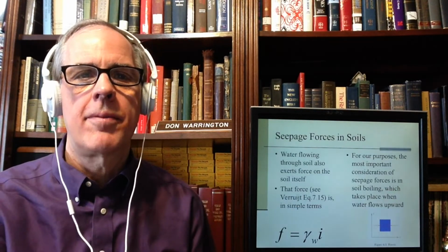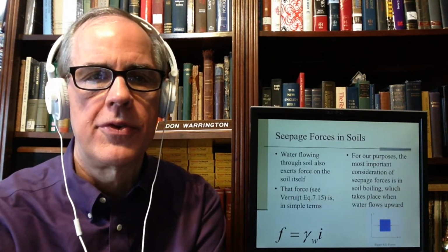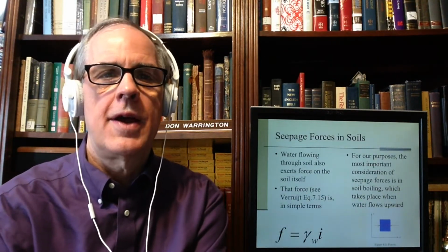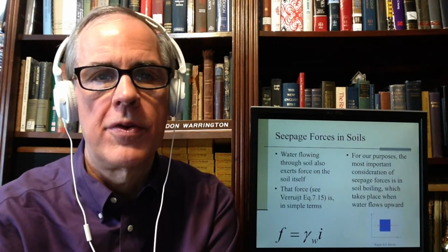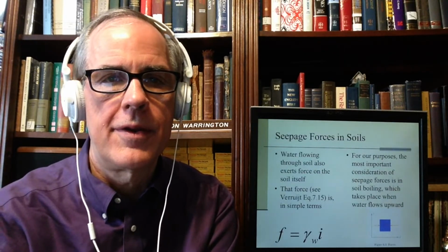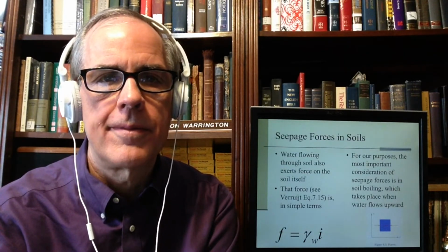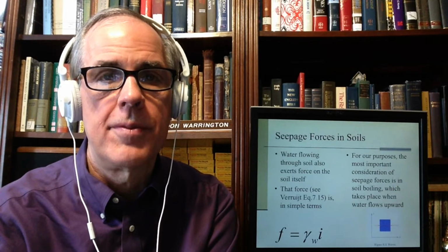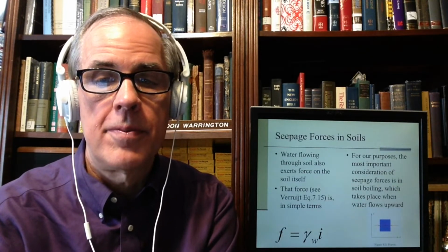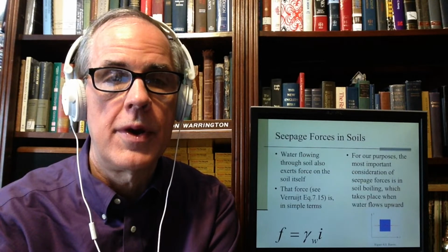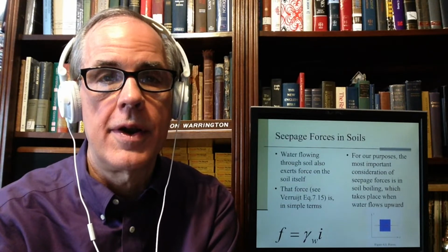Next thing we want to talk about are seepage forces in soils. Anytime water moves through a soil, it exerts a force on the soil, and Voigt has a long treatment of the subject. In simple terms, it's equal to the unit weight of the water times the hydraulic gradient.